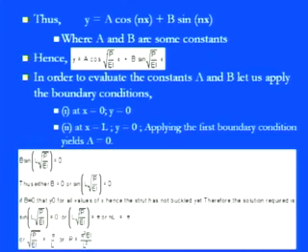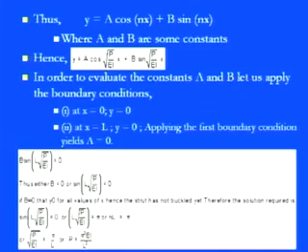So this is the load condition through which we can say that it depends on EI, since pi is a constant term and EI is the flexural rigidity. As I told you in the previous slides, EI is a very important parameter, and another important parameter is the length L of the strut. To check the buckling load, the flexural rigidity EI is considered, and L is the dimensional parameter through which we decide whether it is categorized as a strut or a column. L squared is in the denominator.